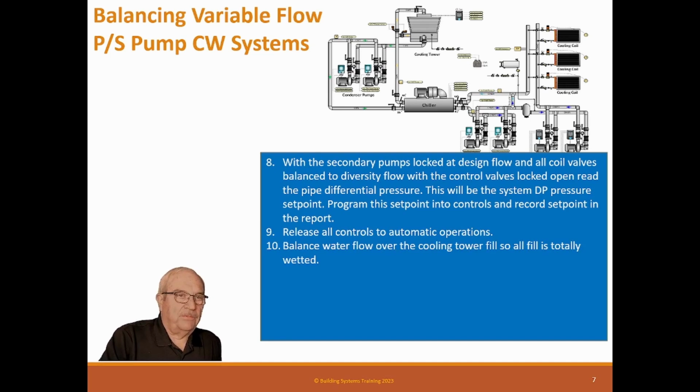wetted. Okay, on the fill, when you balance the water over the top of the cooling tower, you'll notice that the pans up there, or else there might be flow nozzles, whichever, and you're equalizing the flow all around the tower so that it wets the fill evenly. What happens if you allow water to splash onto the fill, and then it wets and dries, it builds scale very, very quickly, and it will scale a tower really seriously.